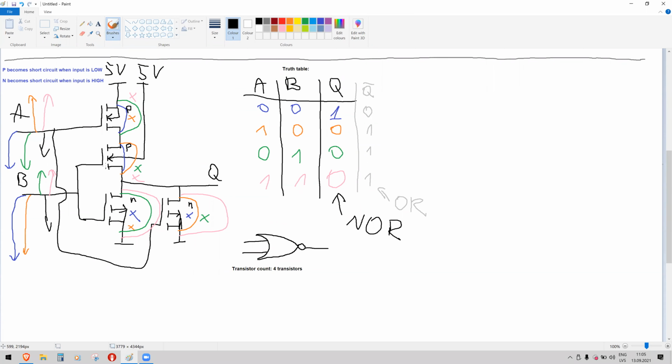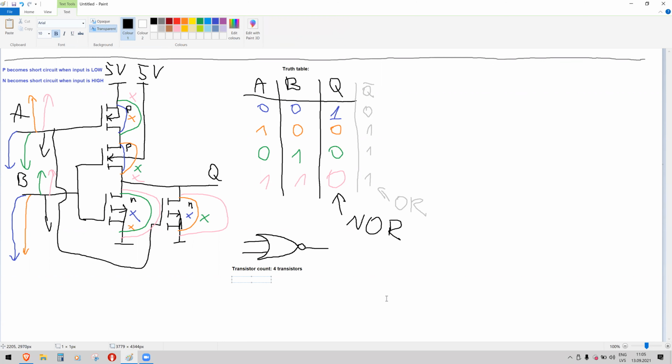All 4 of the gates will receive the new level at the same time, and all of the transistors will start transitioning in parallel. They're not waiting for a previous transistor to change state for the next one to change. This all happens simultaneously. So the propagation delay is actually just 1 tau.